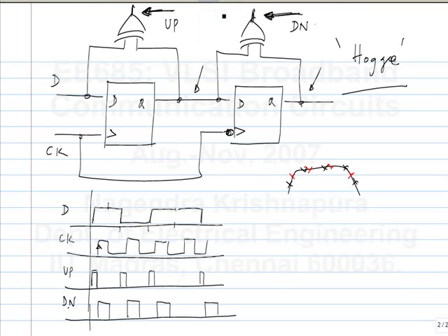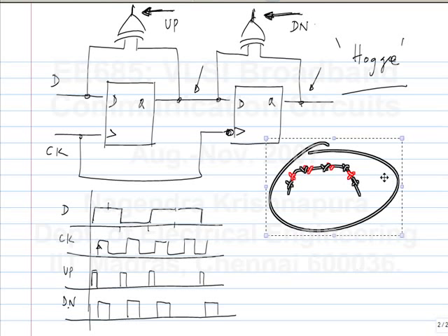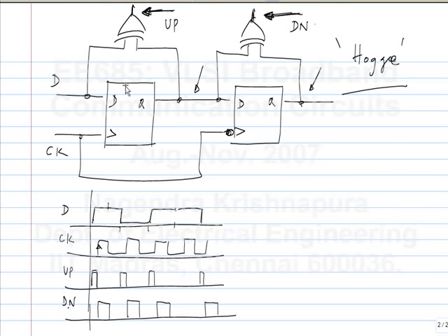That's true. This works for binary data. For PAM data, one simple thing that you can do is just use it as it is. So it will give you something. Basically, you treat the PAM data like binary data. If it is less than 0, it is logic 0, and if it is more than 0, it is logic 1. Maybe you will lose some of the transitions. So you just convert the PAM data into binary data as far as clock recovery is concerned. You will lose this transition information, and you will work only on these transitions. So the number of transitions to work with is less, and we'll see what the effect of that is. So that is one possible thing to do.